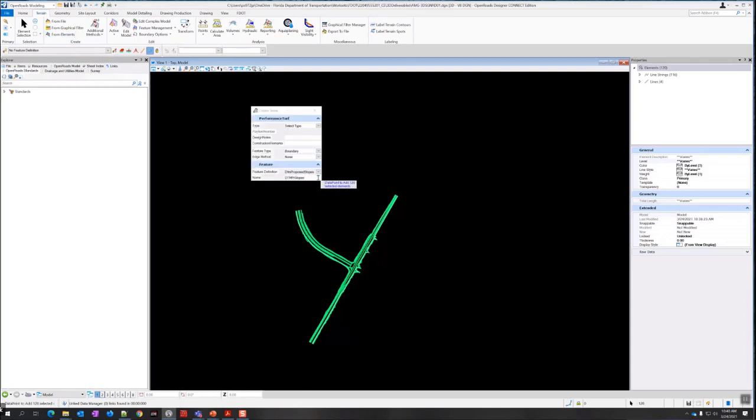And it should say data point, add 120 selected elements. Okay, so that's good to go. Change this feature definition. It's doing proposed slopes. We definitely don't want that. The feature definition should be DTM proposed.